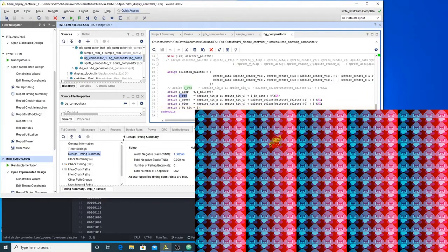And we're going to get this 8-bit value, and we're going to set our red color to the data that we get from the RAM. Technically it lags by one frame, so it's 1 pixel behind, but that's a technicality that we'll worry about later.